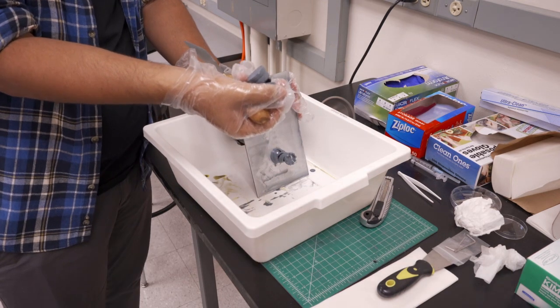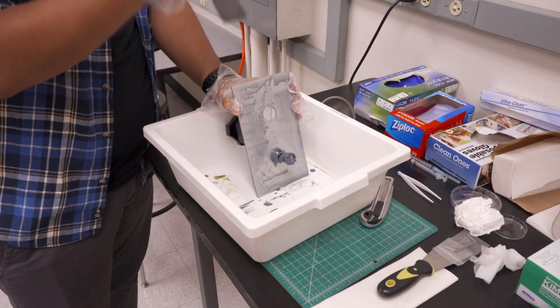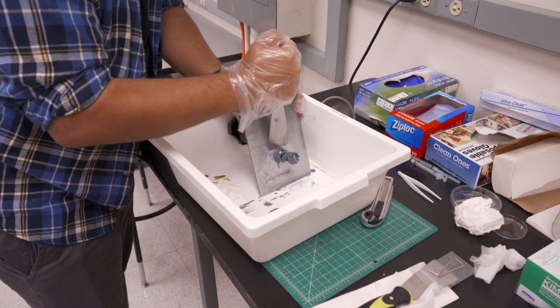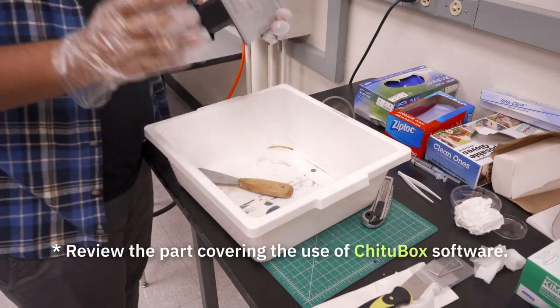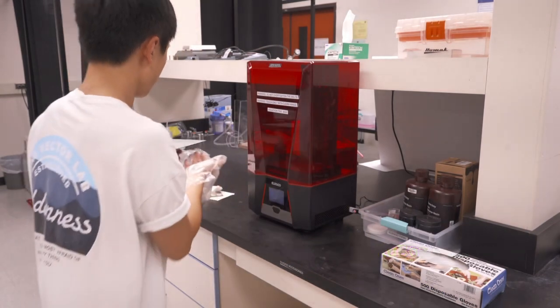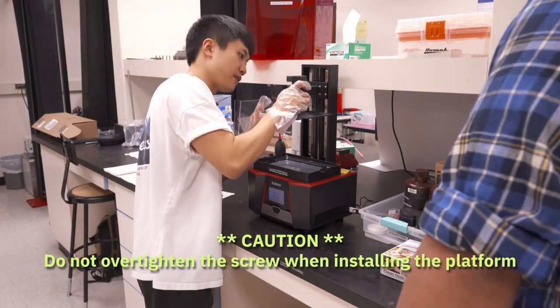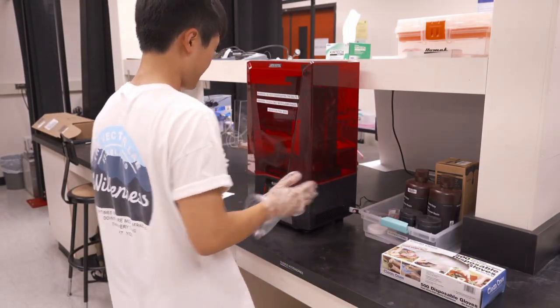Clearly, the bottom of the printed part will be under significant stress during the removal process. Support structure at the base helps reduce damage and makes it easier to remove from the plate, and you can add the support structures in the slicing software. Now you can put the platform back onto the printer. It is a good practice to keep the hood closed whenever possible to keep any contaminants away.